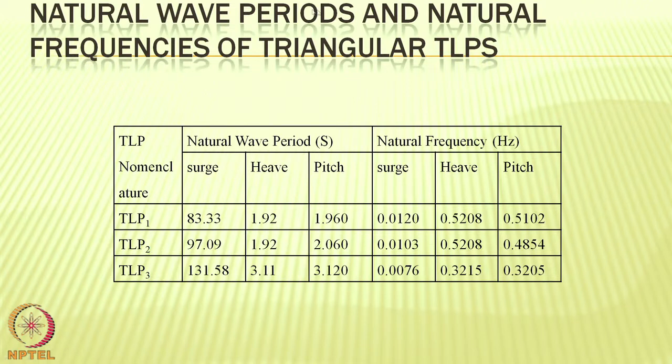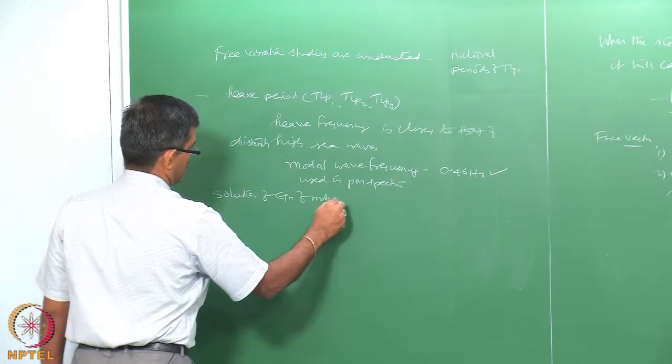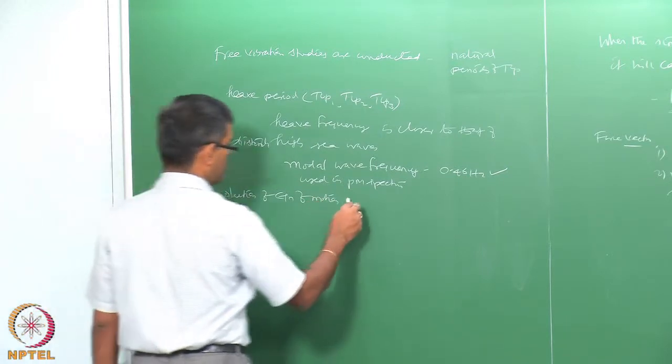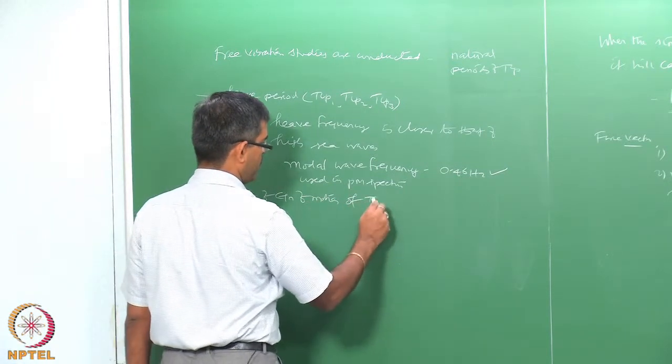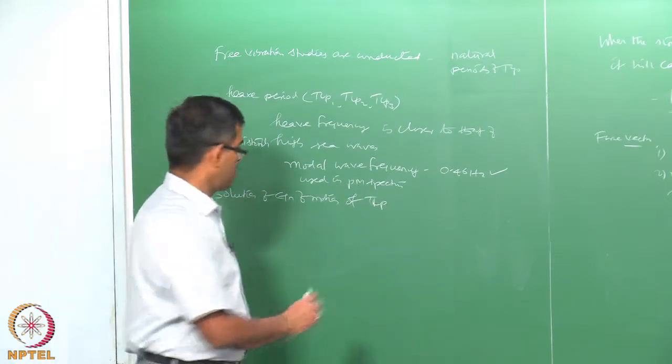Now, the equation of motion becomes iterative, the solution becomes iterative. Solution of the equation of motion of TLP under the combination of hydrodynamic and earthquake loads becomes iterative.